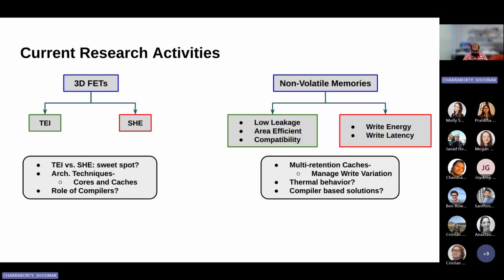Retention is actually the retention time. This is the time span for which your data will not be corrupted, or it will maintain the correctness or remain unchanged while you are storing them on some non-volatile devices. So once that retention time expires, there is a high chance that your data will not be intact as it was earlier. And this retention time has a very good relationship with the temperature. The higher the temperature, the more your retention time will drop. So at high temperature, your data will be corrupted very soon.